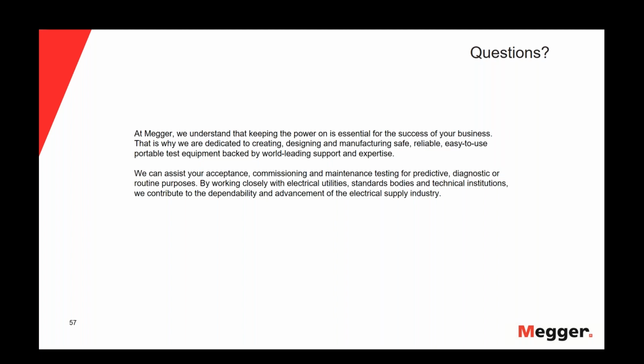It's a very simple answer to give. That depends on the cable. So there is no general parameter for that. It depends on the construction of the cable, because there are all kinds of 15, 25, 35 kV cables. So just go with the manufacturer specifications. The data sheet always contains that. If you buy it from Nexans or Prysmian or whoever you buy it from, they have a data sheet that contains all the information, ratings, and the bending radius. Just adhere to this and adhere to your working practices, and that's the answer to that.